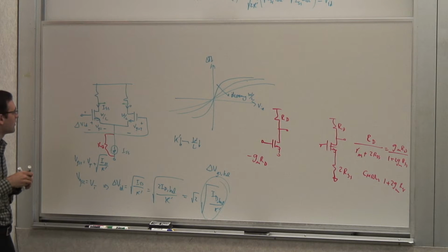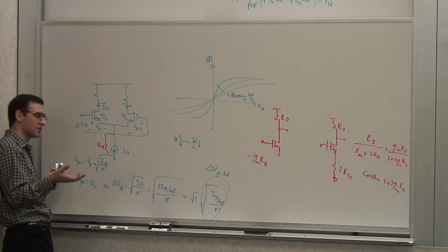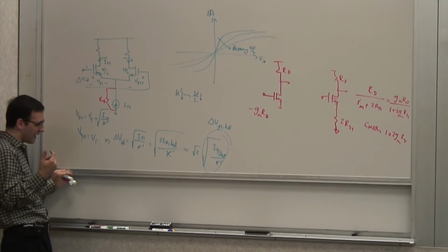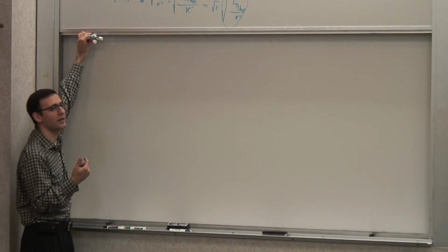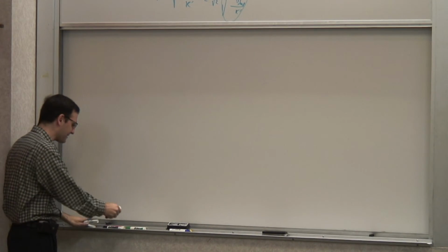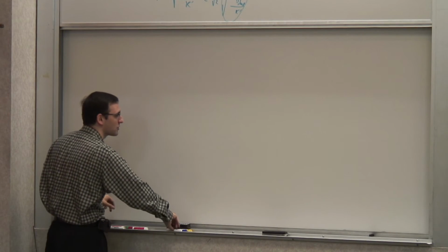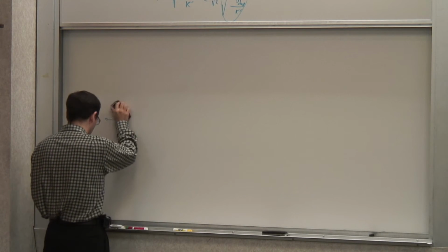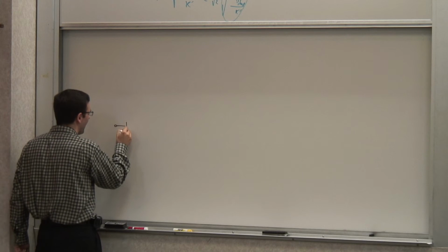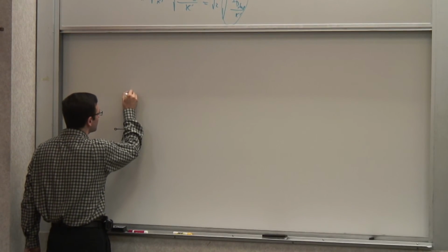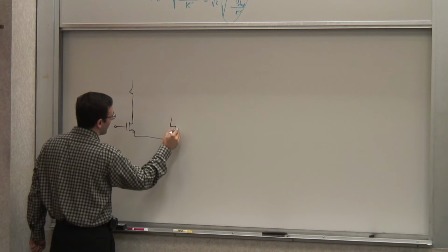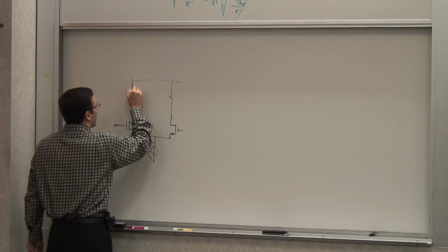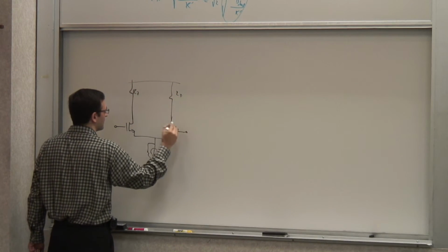So there's a common mode gain by itself, and there's a differential mode gain by itself, but there's no coupling between them. But in reality, something happens that creates the so-called common mode to differential conversion. And that's probably the most significant effect, because usually your common mode rejection itself is relatively high. So let's look at this stage. Let me ask you a question. So I have this stage, could be MOSFET, could be bipolar. And let me just put RD and RD, let's say for now.